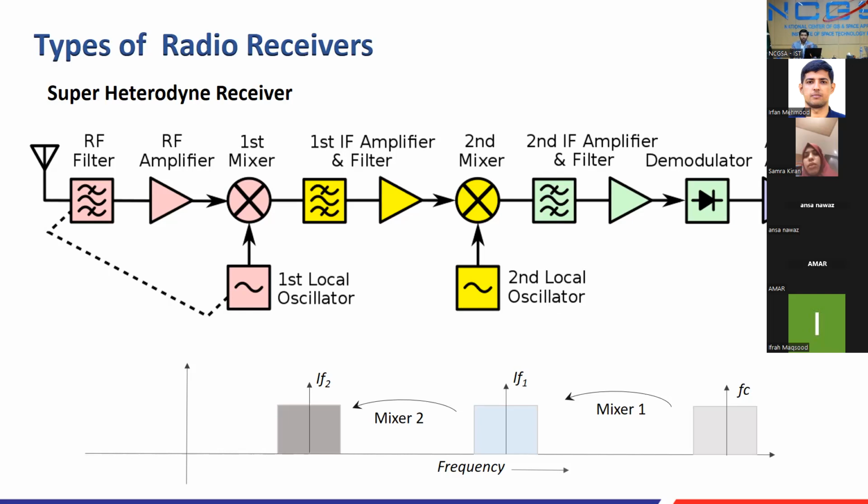So coming to the heterodyne receiver, this is a two-stage conversion, two-stage frequency translation receiver, where you receive an incoming signal, then you translate it first, then you again translate the translation. When we move to the practical example, I think the picture will be clearer. At this stage, you see a demodulator. Because it is an amplitude signal, you are only interested in the amplitude of the signal. So you get the information out of the amplitude using a detector. Your detector could be log periodic or DLVA type. There are many detectors available. We mainly use ones from Analog Devices for this application. So that was the heterodyne receiver.